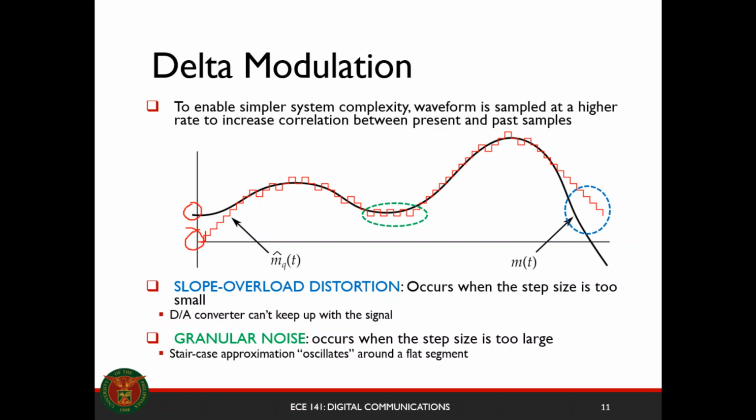Once your delta modulation exceeds the current value, it will decrease by 1 step. But the problem with delta modulation is the presence of this. If we have a slowly varying signal, then your delta modulation will just cycle between 2 states on and on. So we call this the granular noise.